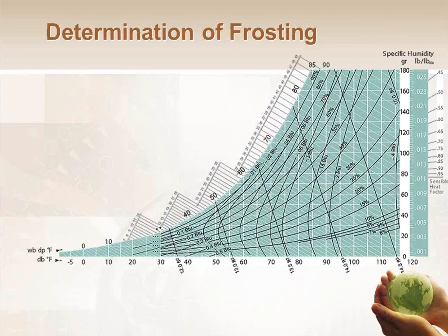Because we are reclaiming moisture, and that moisture is going to be transferred to outside air, and that outside air could be below freezing, we do have the potential for frosting up the wheel. It's very simple to predict when we're going to have a frost condition.